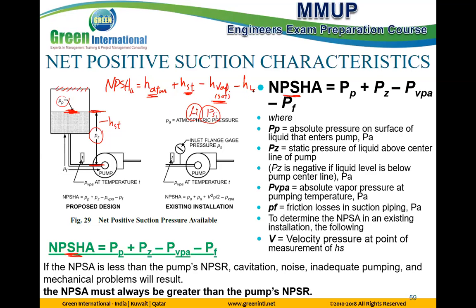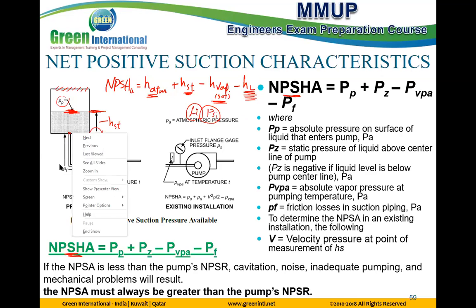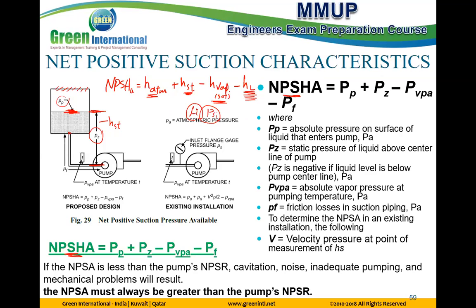Last part, this is the losses. You remember the equation of the losses? These losses should be calculated for the pipe from the beginning here up to the end here for the suction loss. It means all these terms are related to the suction side of the pump, till the end of the suction side. So H losses here is calculated for this pipe.